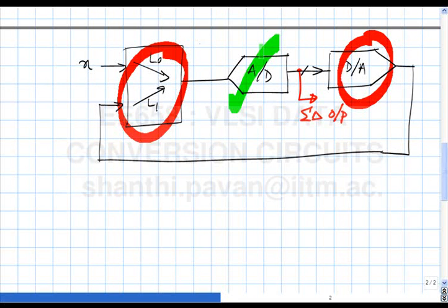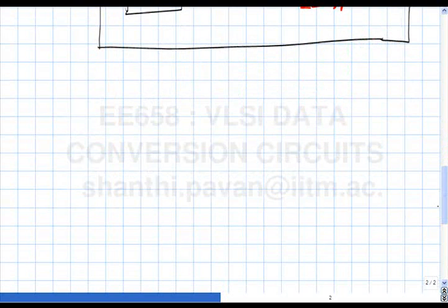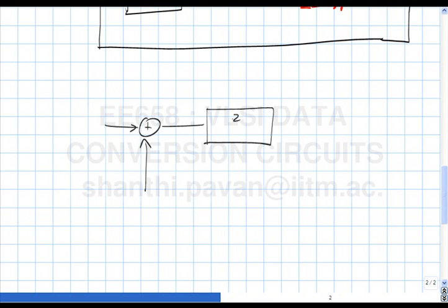The DAC, again, there are many ways of implementing it. One of them is a current steering DAC. That also I'll gloss over very quickly a little later on. The key point is the loop filter, which we have not figured out up to this point. In the simplest case, for example, an example of a loop filter was this one here, where I pushed the Z inverse delay that the quantizer gives you into the loop, and this is the quantizer modeled with an additive white noise source.